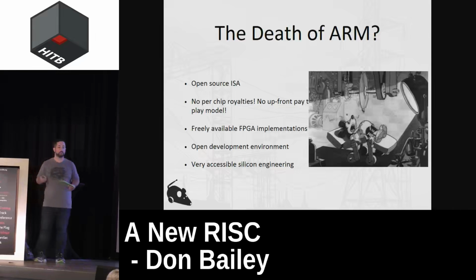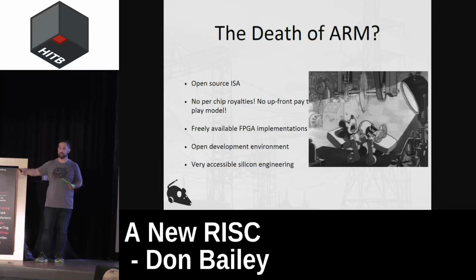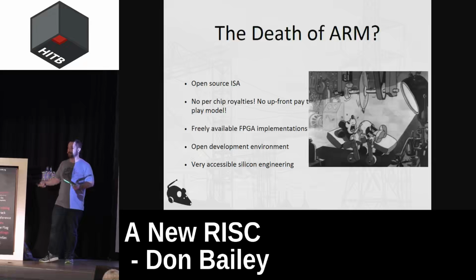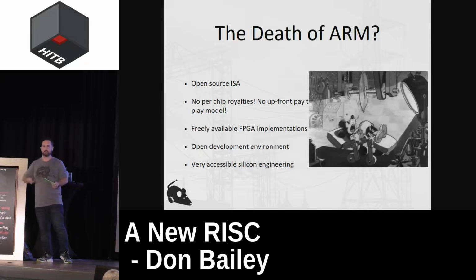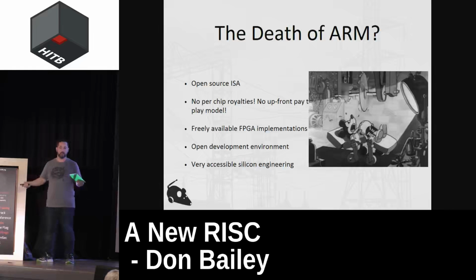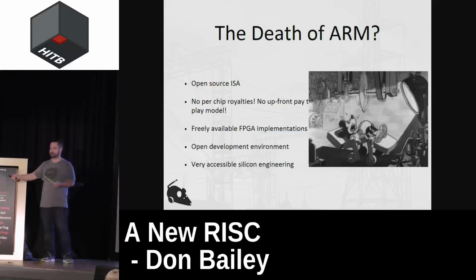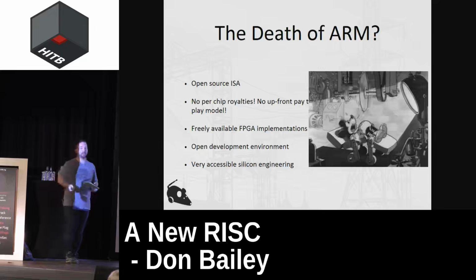But the problem is, when you get to an ARM Cortex-M23 or M33 level, the amount of money that you're paying per chip for that TrustZone is about the same as you would pay for a Cortex-A9 or a Cortex-A5, albeit probably without TrustZone. Still, you might as well step up in capability and get a real processor instead of running a microcontroller, because that's nonsense. Like, why would you pay that much for it? You might as well just step up your capability and run a processor at 1 gigahertz instead of 48 megahertz or 100 megahertz. There's no reason to spend that money.